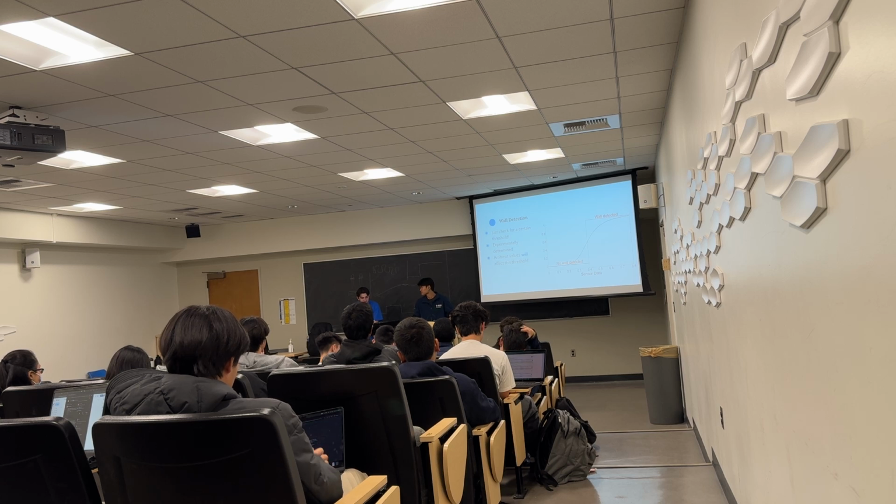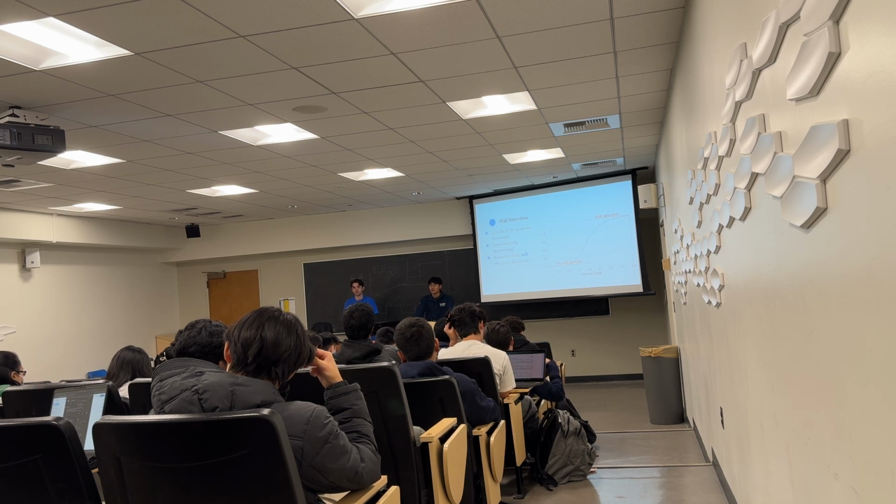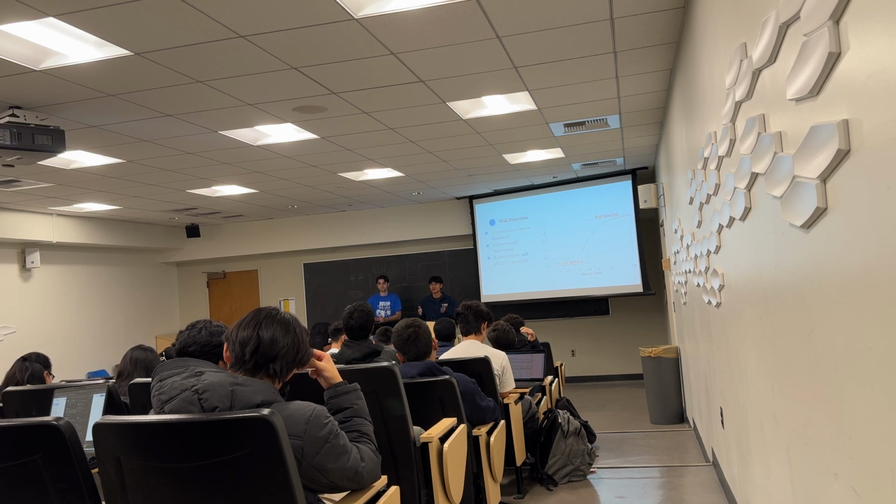If you're really advanced, you can add functionality where you place the mouse in a spot in the maze, press a button, and it saves the value for how far you should be from the wall. But this is all just to detect walls, and eventually you're going to use these values for your algorithm, where you make an image in your mouse of where the walls are. That seem good?